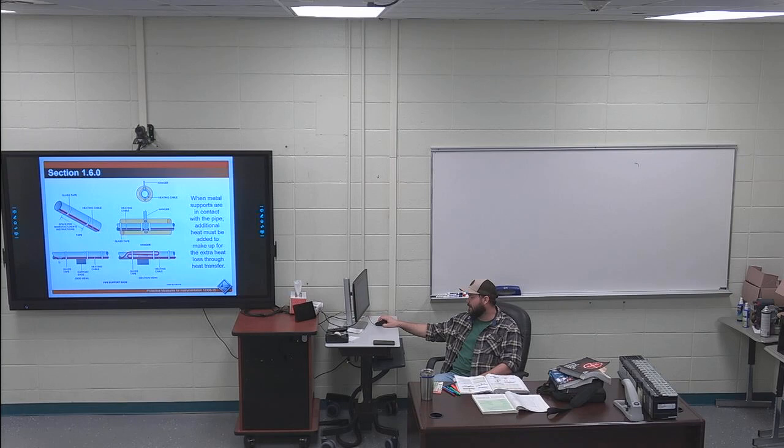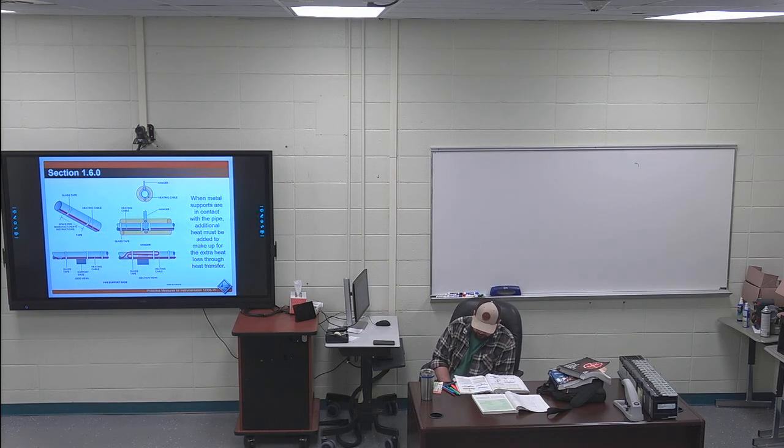By entering from the bottom, water shouldn't go up, so there's less of a chance of this filling up with rainwater or something like that. So you enter the bottom half of the pipe with your cabling when you're installing.